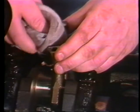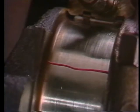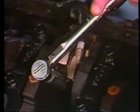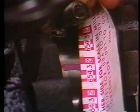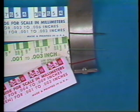Plastigauge is a small strip of plastic that is placed between a bearing and the crankshaft to measure its oil clearance. The less clearance there is, the more the plastic is crushed. Before using Plastigauge, both the bearing and the crankshaft must be cleaned of oil and dirt. After placing a piece of Plastigauge across a bearing surface and torquing the cap in place, carefully disassemble the bearing and compare the crushed Plastigauge to a scale on the Plastigauge sleeve. If the Plastigauge does not crush, or if it crushes too much, a different size Plastigauge must be used.